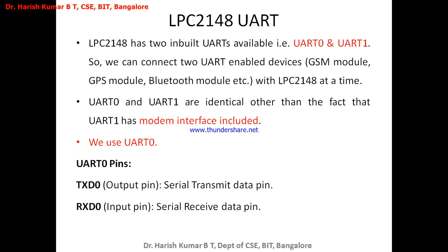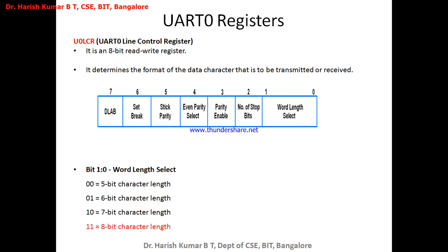Important. Now LPC2148 has got two UARTs, UART 0 and UART 1, and we are using UART 0. Now for UART 0, the important registers are U0LCR, the line control register. Using this register you define the format of the data. You are saying a sequence of 8 bits forms a byte, and by making the second bit 0, you are saying there should be one stop bit, and you are enabling the Divisor Latch Access Bit. And then